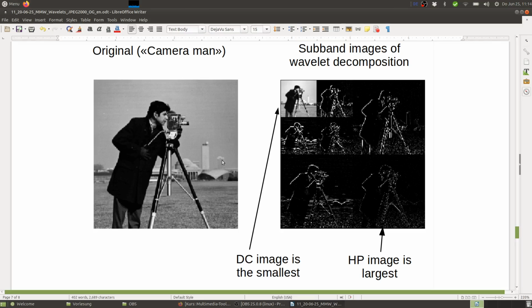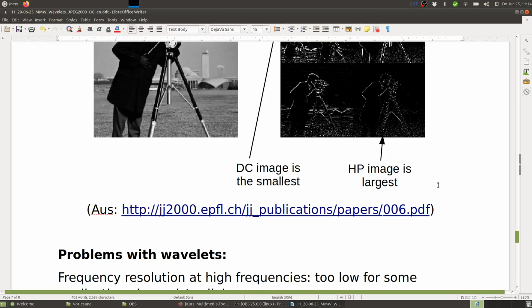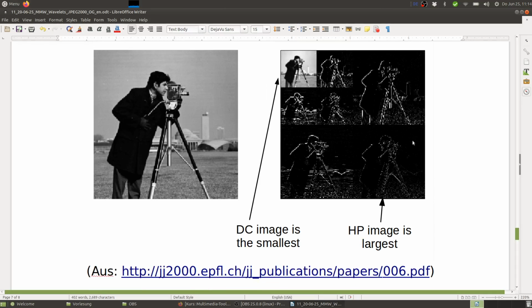So for the grassy areas, we could as well use the DCT. It wouldn't make any big difference, except for the blocking artifacts. The wavelet artifacts would still look more natural. Yeah, so I think this basically shows nicely the principle of the wavelet decomposition as opposed to the DCT decomposition. Remember, for the DCT we had the Ilmenau test image, and there we had uniform sized subband images.